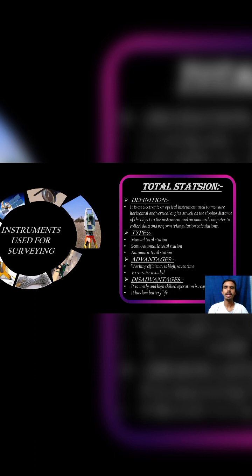The next instrument is total stations. It is an electronic or optical instrument used to measure horizontal and vertical angles, as well as the sloping distance of the object to the instrument, and an onboard computer to collect the data and perform triangulation calculations. Types of total stations: manual total stations, semi-automatic total stations, and automatic total stations. Advantages: working efficiency is high, saves our time, errors are avoided. Disadvantages: it is costly, high skill operation is required, battery life is low.